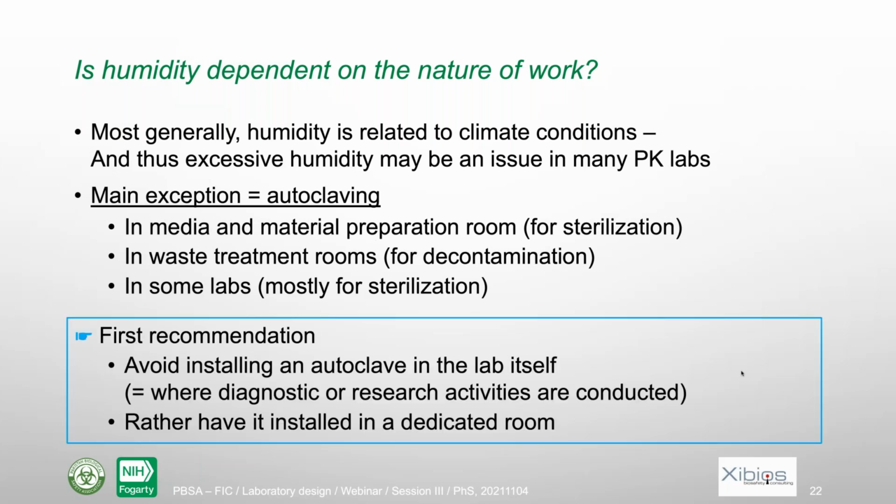So a first recommendation would be to avoid installing an autoclave in the lab itself, especially not in labs where there are some diagnostic or research activities. So it would be either in a sterilization room or in a decontamination room, but not in the lab. Okay, and so it should be in a dedicated room if possible, so that you don't create a humidity and heat problem inside of your lab. Okay.